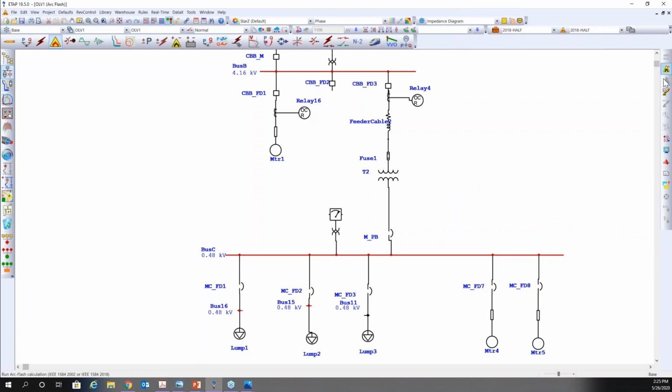So we're going to put a fault on this bus now, and what we've done here is exactly what we've said before. We've got 51 milliseconds, so we've got a fault on the load side of this breaker in the cable compartment, and we've only isolated this breaker, feeder number 1. We didn't open the main coming in. So we're at 51 milliseconds and 3.03 calories per centimeter squared.